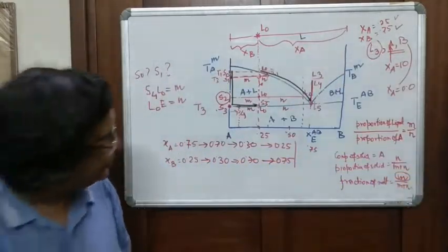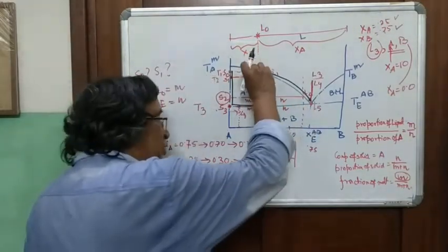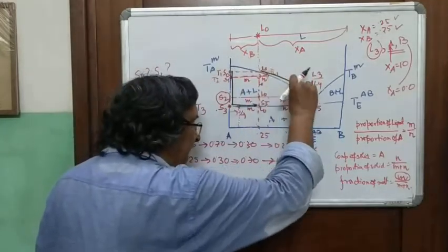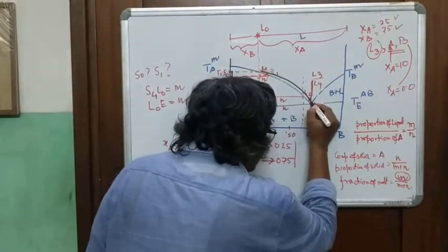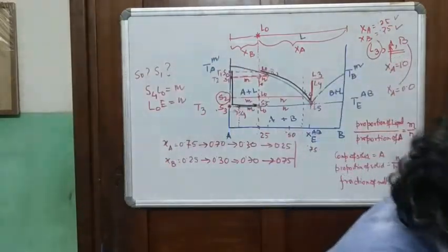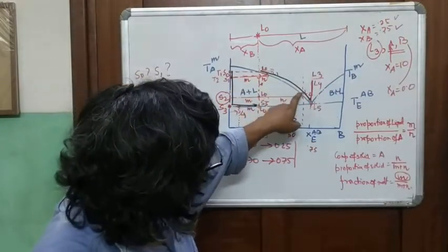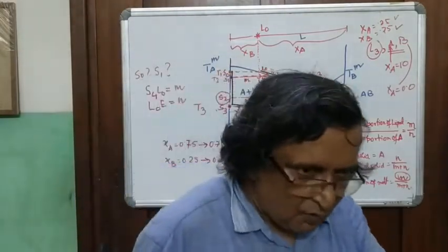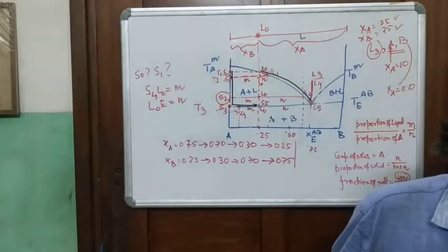First the solid. What happened to the liquid overall, you can see. The liquid overall moved on this side. That means overall it became B-rich. But the moment the liquid reached the eutectic, its composition did not change anymore. I can't show this because the liquid will always remain here. So the liquid composition changed, became B-rich, reached the eutectic. Once the melt reached the eutectic, the composition of the melt could not be changed anymore.